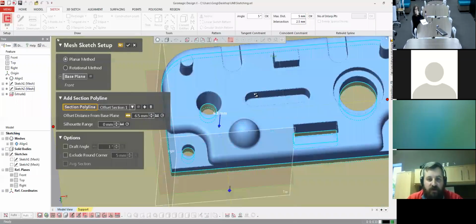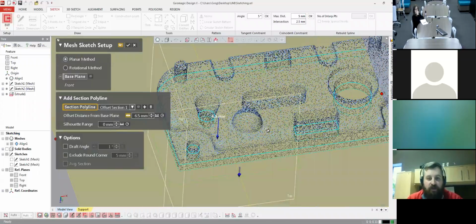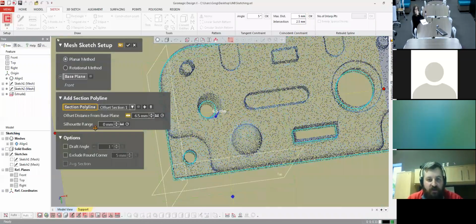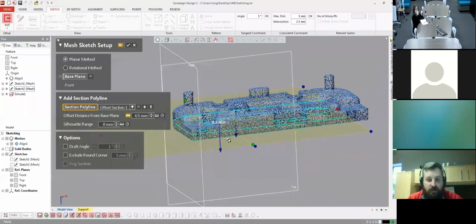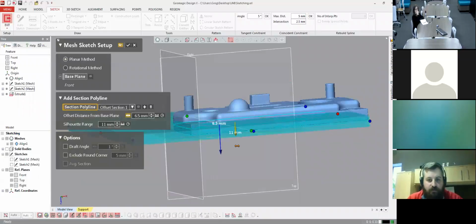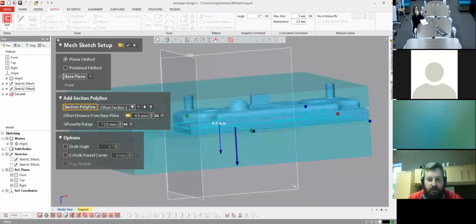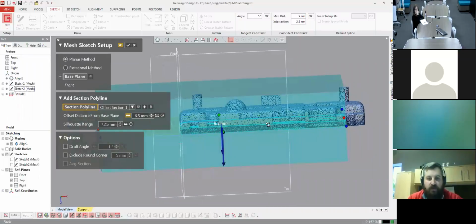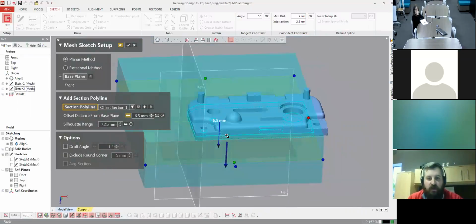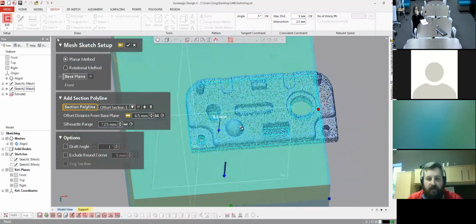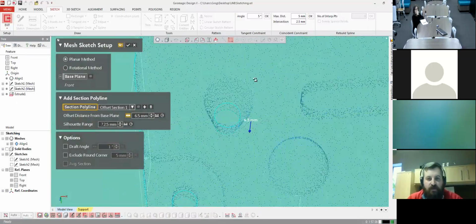So what I want to do is get that smallest hole size accurately. What they have in here is what's called silhouette range. And that silhouette range, this is where this small little arrow comes in. If I pull this arrow, you can see it grabs all the data through this complete volume. So I've got this giant rectangular volume here. And if you notice, it finds the smallest diameter throughout that entire volume.